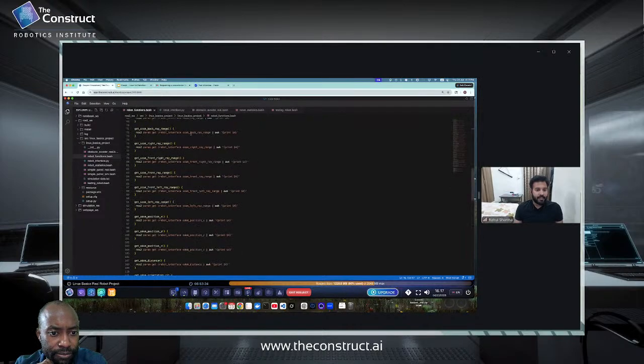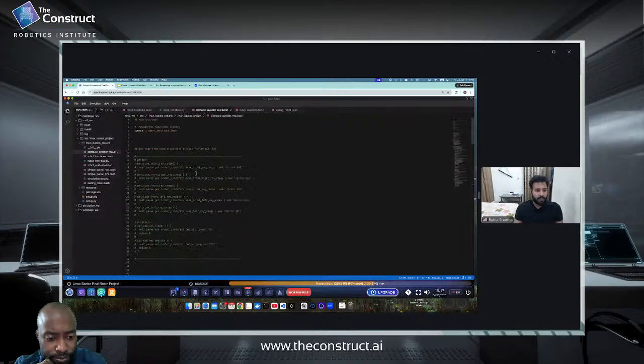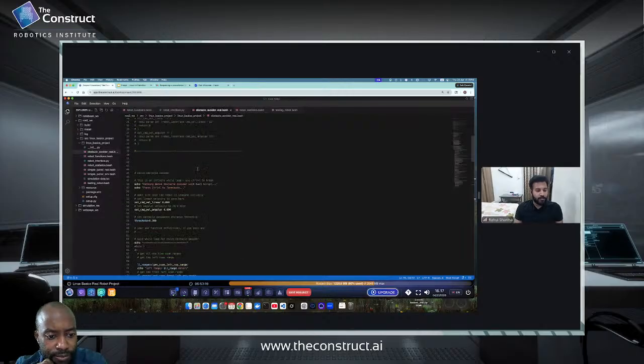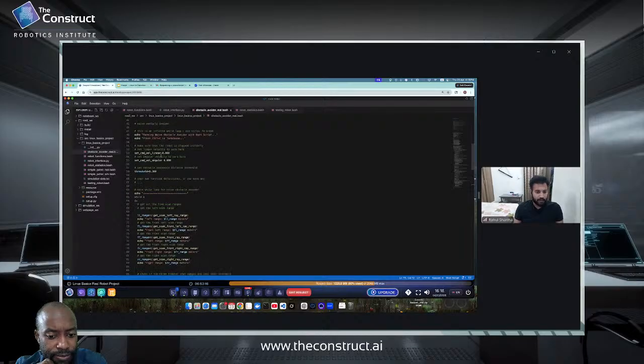All the getters and setters will be imported in this file also, and available here, which we will use later in the code. First we print these two lines: running naive obstacle avoider with bash script, press Control C to terminate. Then with these two setters, we set the linear and angular velocity to 0 to make it static. And then we stored the 0.300 value in a variable named threshold, which we will use later in the code.